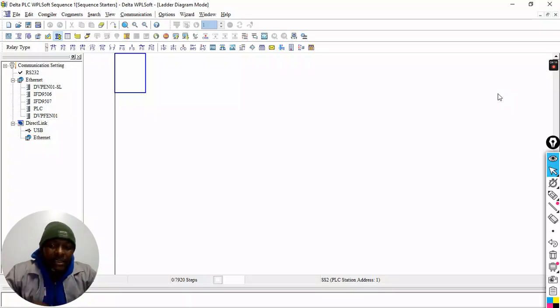That final line is not okay. It suggests 1 stop button for both motors. Different starts, but 1 stop button. So I will do it like that. I will follow that part, even though I'm not happy. Each motor should be independently started according to this, and then independently stopped. But here it says stop button, so we are going to go with the text, and we are going to use 1 stop button. A stop button, emergency stop. So we are going to use 1 emergency stop.